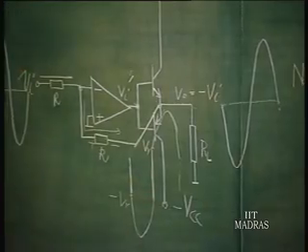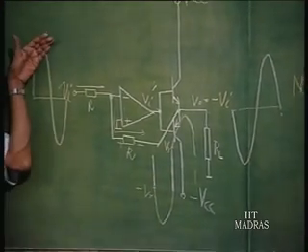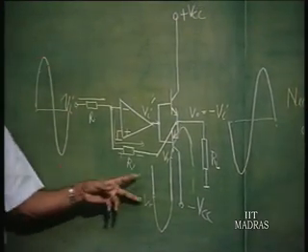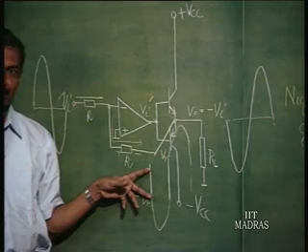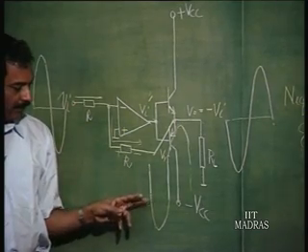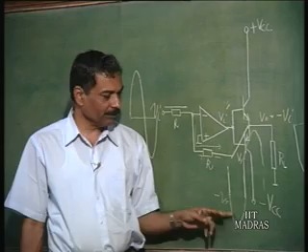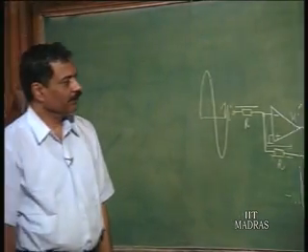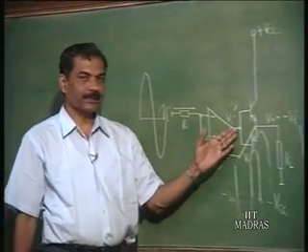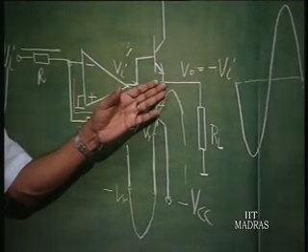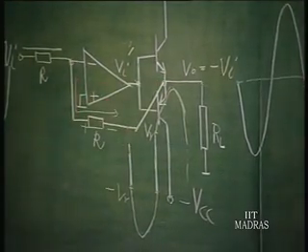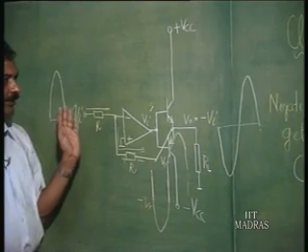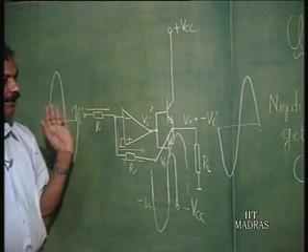So, even if this voltage is of the order of hundreds of millivolts peak, even though this is going to be of the order of 0.6 to 0.7, that hundreds of millivolts peak will be superimposed over this in this manner. So, this is what is called pre-distorted drive for this, so that the output is going to follow the input, as though the negative feedback is all the time there.